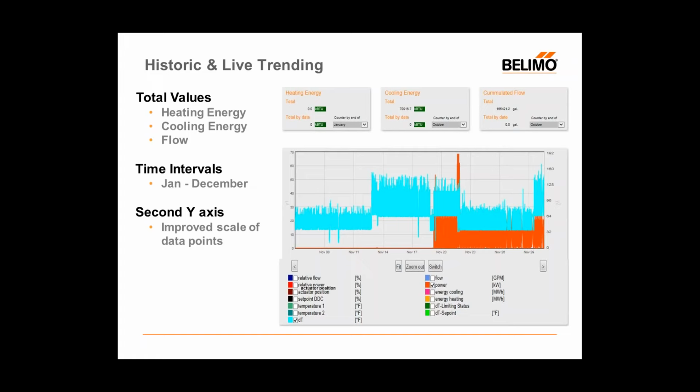Something that will happen if you go into an override mode is we will start to count a timer. And that timer is going to last for 2 hours. Once that 2 hours expires, we will go out of whatever override mode has been selected and into auto mode. So there's no way a technician can go in, override the valve open, pack up, leave the job site, and accidentally leave that valve wide open, say, for the entire weekend. We will time out, and that will get us out of our override mode and back to auto regardless of what is going on.